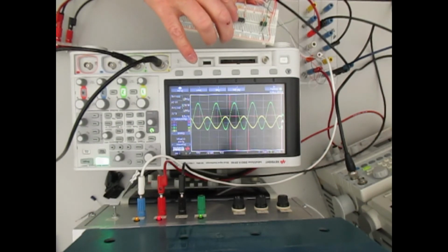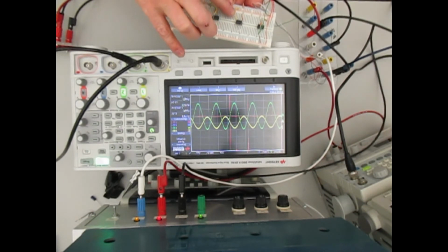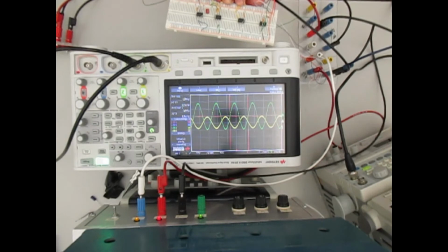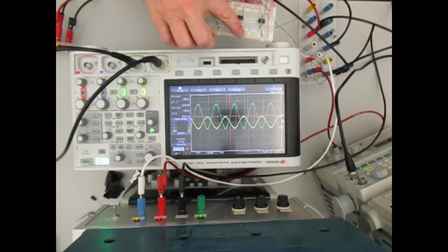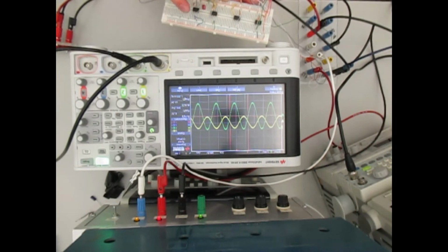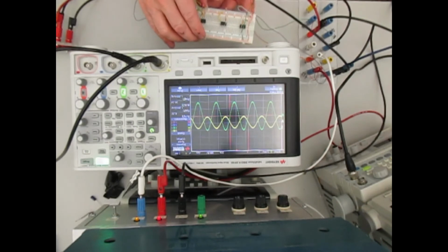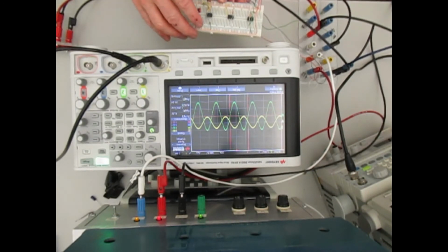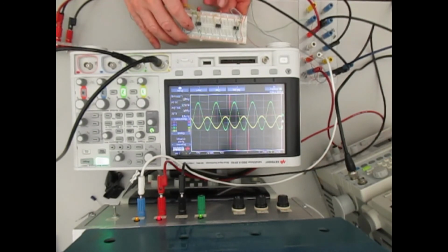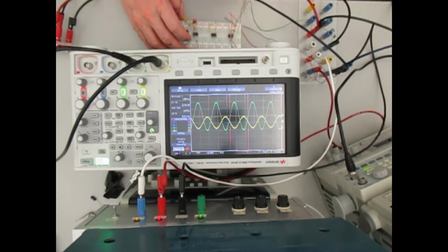So if I plug my IC in here, you can see this one yellow wire is plugged in the same spot as this pin. So they're making a connection. And then it's coming down to the minus 12 volts here. There's my plus 12 volt connection here. That's pin 4 and 7. And then you see our connections to pins 2 and 3. And oh, we're missing a connection there. I don't know who wired this one up. I had some grad students helping me. I'm sure it's obviously their fault, right? Okay, I'll take care of that.